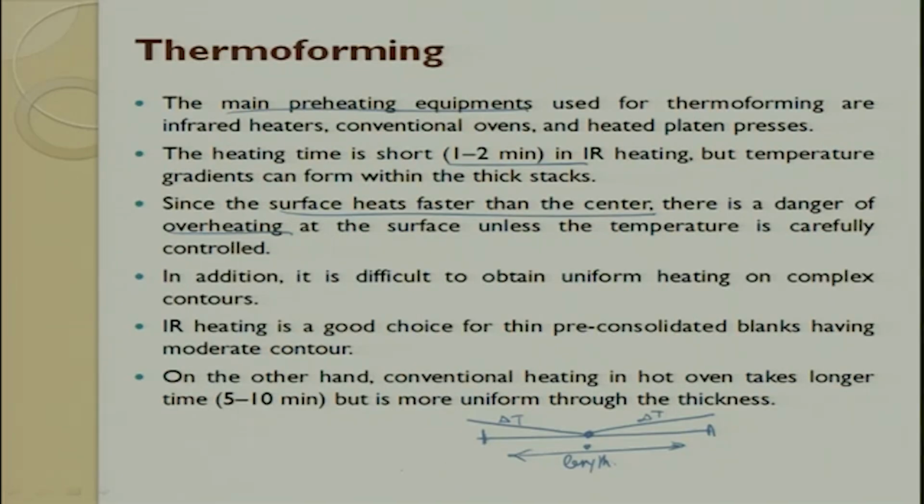So, in order to have a uniform distribution, a complex heater is made. That means the heater has a contour shape, so that it makes a uniform heating of the die. So, IR is heated and then it is used for consolidation.